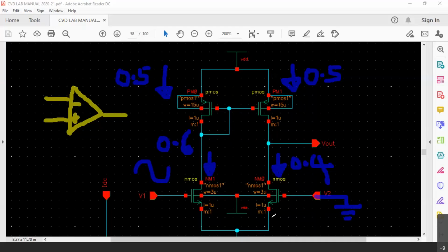Now here, when the gate to source voltage is slightly affected, it is being reverse biased by the inflow of 0.1 milliampere at the other branch. At the bottom it has to be 1 milliampere only, in this manner. Total it is 1 milliampere only. Now when this left side current increases, it is opposing the right side current. That is how this V2 slightly moves towards cutoff region, and because of which current here reduces. And you know that when the device moves towards cutoff region, the voltage at the output increases.